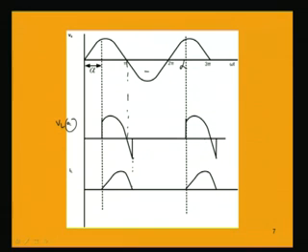So, we have seen that there is voltage available across the load even after the 0 of the input voltage is crossed to the negative side. This is a disadvantage, or actually this should not happen, because we are having a controlled half wave rectifier, but here in the negative half also there is voltage available across the load.